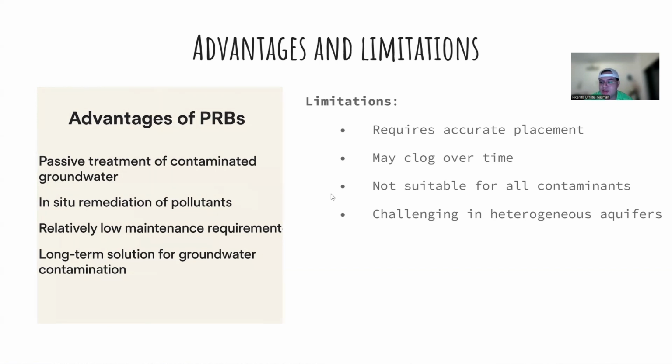Some of the common reactive materials included in this process are zero valent iron, that is for chlorinated solvents and metals. Also activated carbon, that is for organic compounds, and also limestone or zeolites, that is for acidic or metal-laden waters. Also, some of the limitations